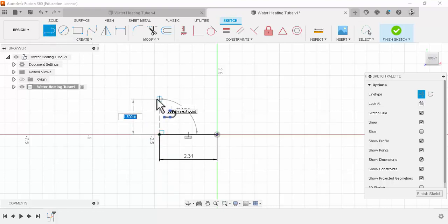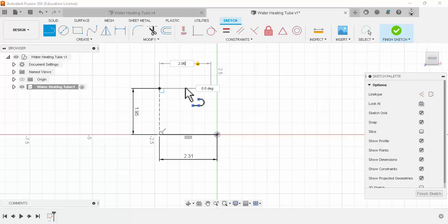We're going to make this line the diameter of that curve, 1.95. Hit enter. Hit X again to turn off the construction. And then this one is going to come straight over. We said the entire length was 2.06. However, that included our taper, so we need to subtract that 1/4 inch taper from the end there, and that will give us our total length there.